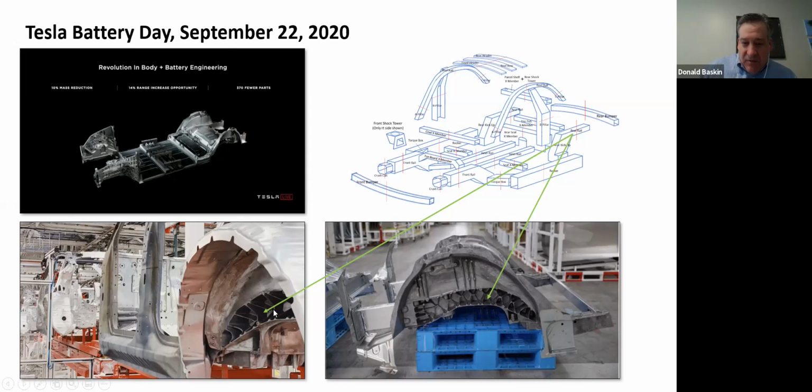So this is the rear rail, okay? This is this structure right here. I'm showing you right on the schematic I showed you previously. This is this rear rail structure right here. And they've got sort of this waffle structure right here. This is a casting. Let's see if you can figure out the slight miscalculation here, why this may not be the best design. I'll give you a minute to think about it. Think about this body structure being under torsional loading.